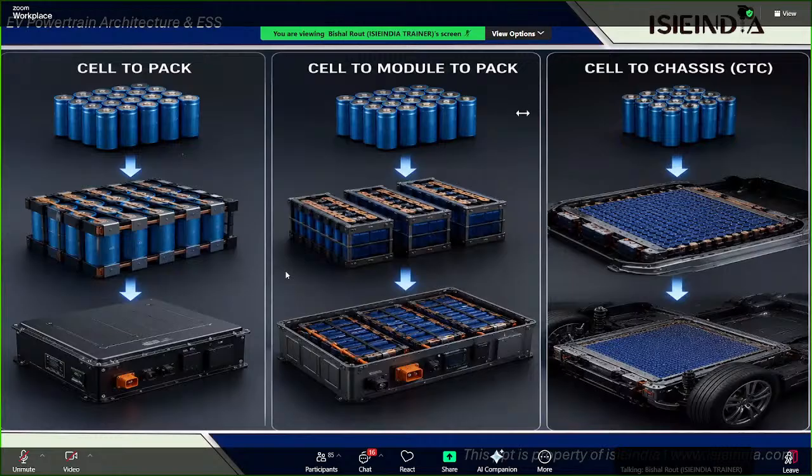It is okay. I had seen many vehicles utilizing the CMP approach. But again, there are some rules and laws that have been written. So you have to go through the rule books as well, right? It is not that I'm saying it is approachable; there is a rule book for every go-kart range. So you can go through those rule books, whether they are allowing it or not. Based on that, you can go for it, right? The majority I saw are going for cell to pack, because it is easier to manufacture, rather than the cell to module to pack approach.